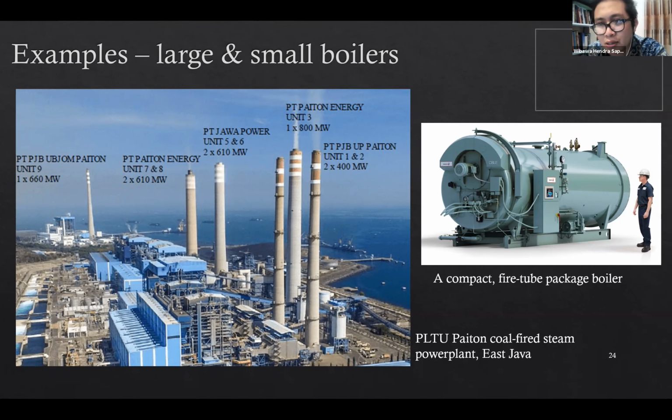You need to consider several parameters for choosing the type of boiler. The first is the particle size of the solid fuel, the second is the emissions that are generated, the third is the capacity of the electricity generation, and also the combustion temperature. It's very important also. As Pak Wawan stated, the combustion temperature is very important, especially when we want to reduce emissions, especially NOx.